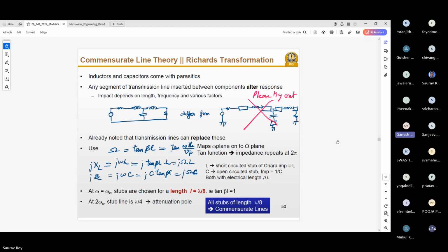Yes. I think it should be possible. See, in the PCB, when you start fabricating between two layers, it just forms a capacitance. Yeah, right. But that capacitor is already part of the microstrip line. It's not any extra thing you are bringing. If you have to add something additional, you need to have an additional microstrip line.